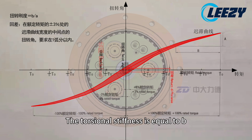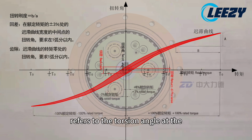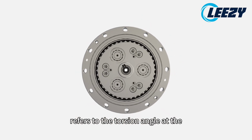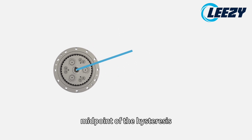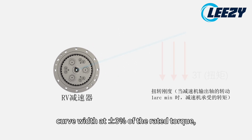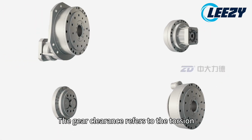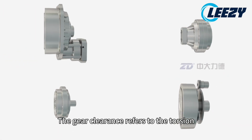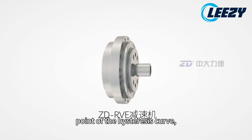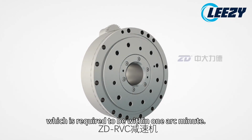The torsional stiffness is equal to B divided by A. The backlash refers to the torsion angle at the midpoint of the hysteresis curve width at plus or minus 3% of the rated torque, which is required to be within 1 arc minute. The gear clearance refers to the torsion angle at the torque zero point of the hysteresis curve, which is required to be within 1 arc minute.